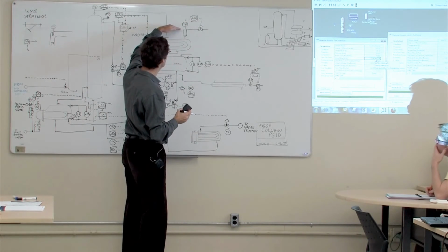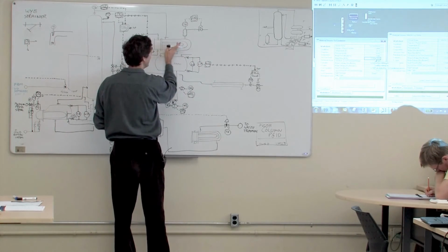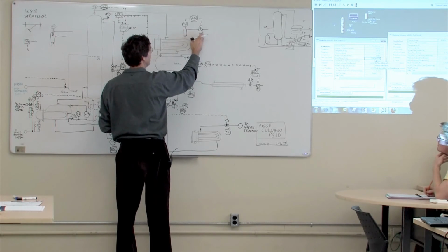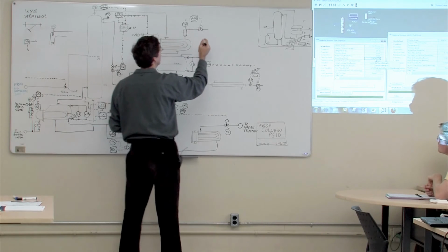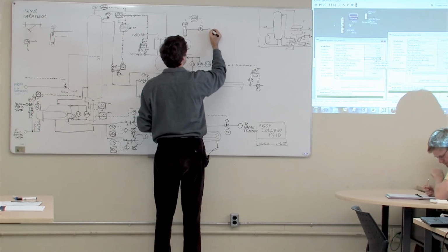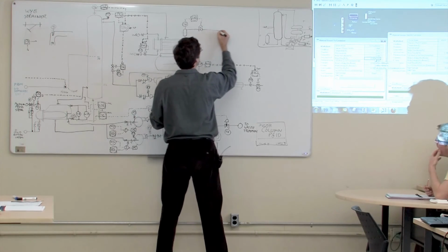So if the temperature starts to drop, it opens the vent, and away it goes. And then what happens is the methanol gets sucked up into that area. It starts to vent a little bit of methanol, and the TE heats up, and then the control system sees that and closes the valve again. So, and that's going to go off to our waste heat boiler.